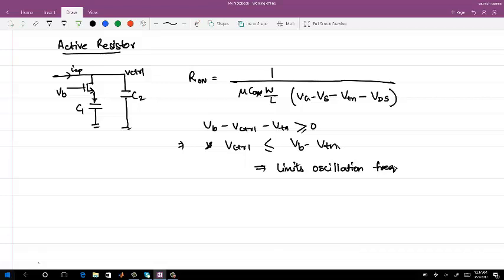Yeah, but it can go only to VDD, right? No, so let's see that. If VB can go to VDD, you take a 1 volt process, right? For a 1 volt process, your VTH, what technology? 65 nanometers, 300 millivolts minimum. So you are basically at 0.7.